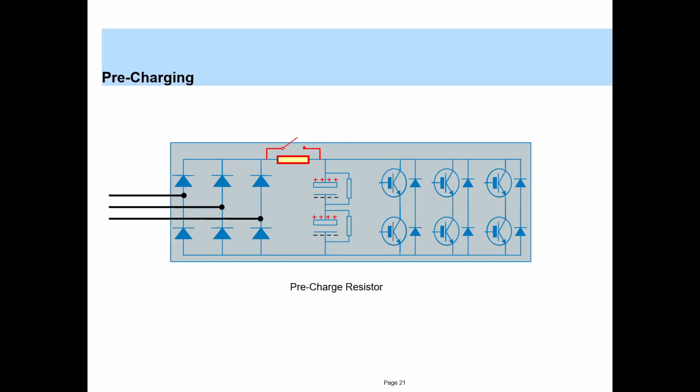which is undesirable. Hence what we do is, there is a resistor initially. When the supply is switched on for the first time, the path is taken through the resistor, so that the surge of current is reduced, and gradually the capacitor charges. When the DC link or the capacitor is charged, a relay is operated and this resistor is bypassed.